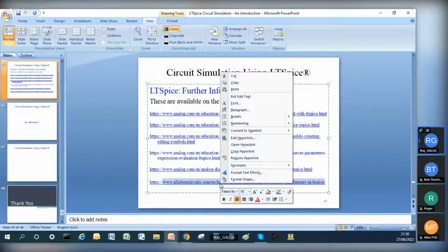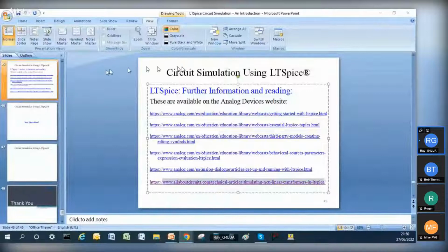Is the coupling factor K on there? Is that purely designed with respect to inductances, or could it be used for any mechanism of coupling between two points? Well, the coupling factor is basically telling you the goodness of the coupling between the transformers, between the windings. It's an expression of mutual coupling. Which means it could be a transmission link for anything you like. Yeah, it could be. I mean, it could be an ATU. You could have an air wound coil, in which case you don't have to worry about non-linearity.